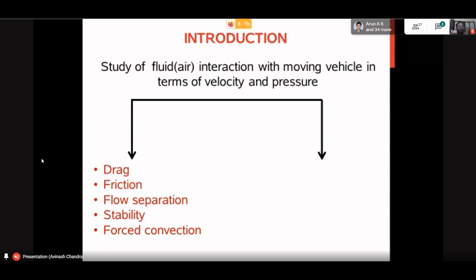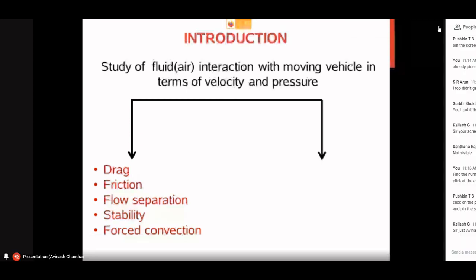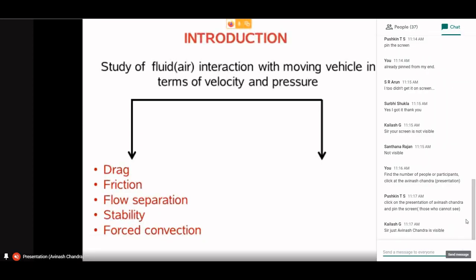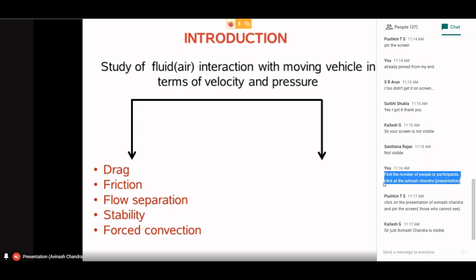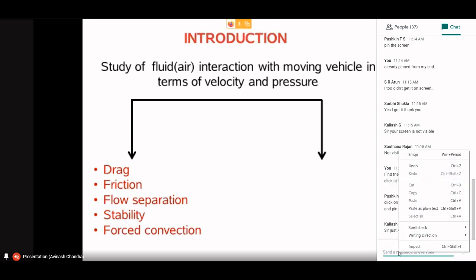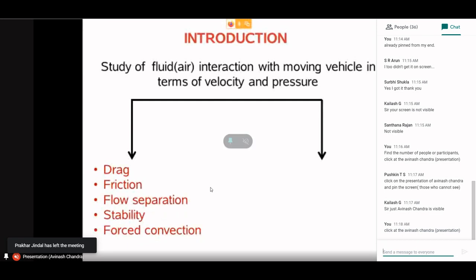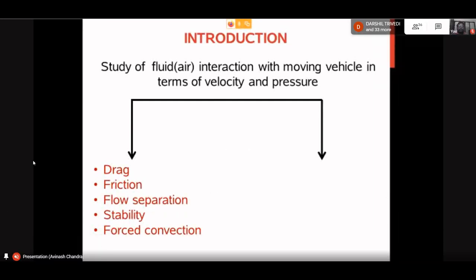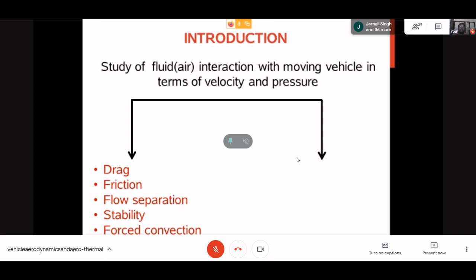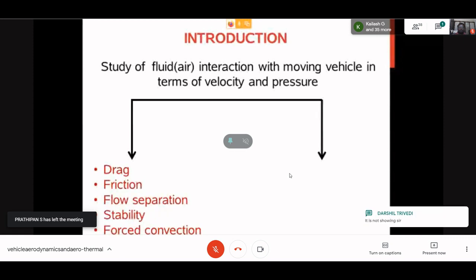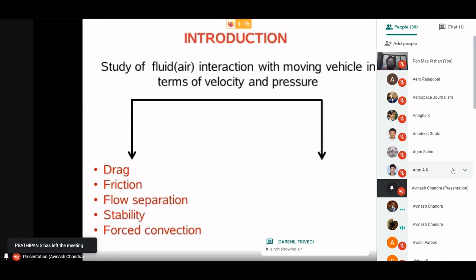Then we have flow separation. The object interacts with the fluid, and then the fluid will leave the body. Since it is not a perfectly smooth body, and the flow is not going to stick perfectly, it will have some kind of effect when the flow separates from the body, some past-body effect. How those effects are going to affect the aerodynamics is very important. In fact, the flow separation phenomenon is very important in terms of your stability and the flow physics.